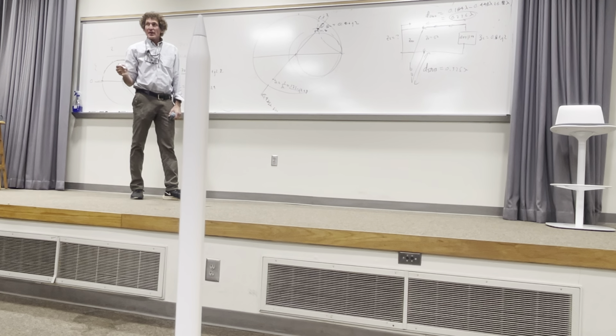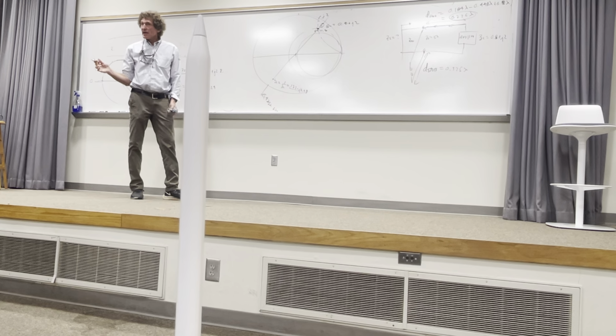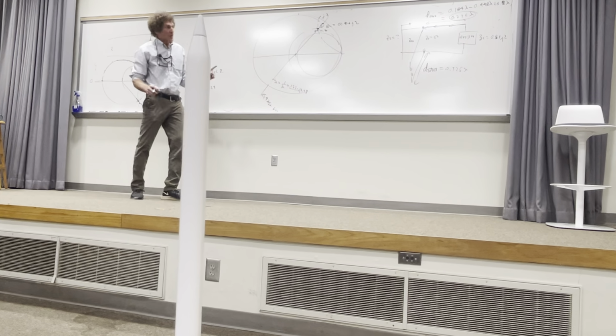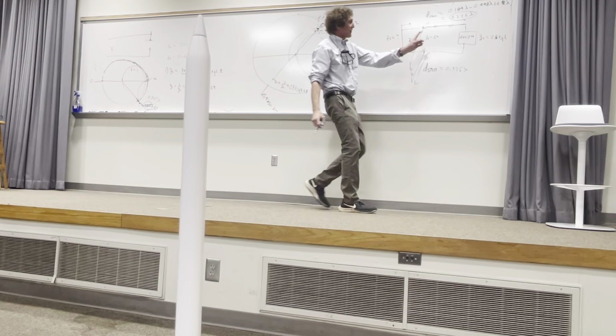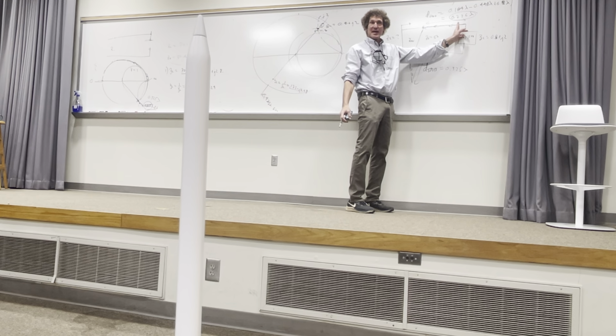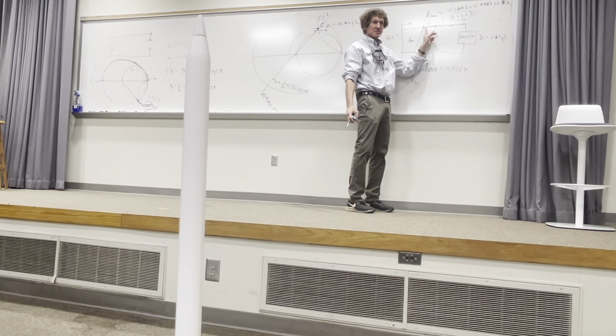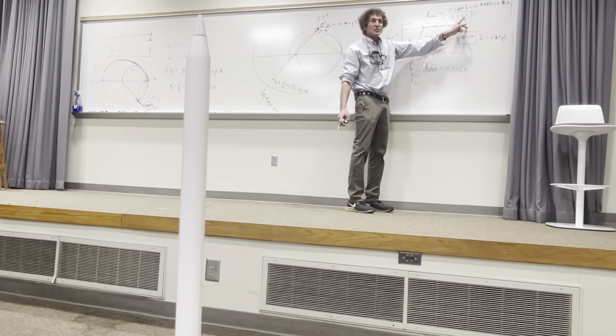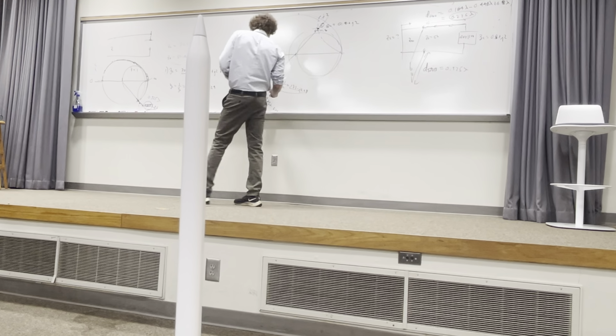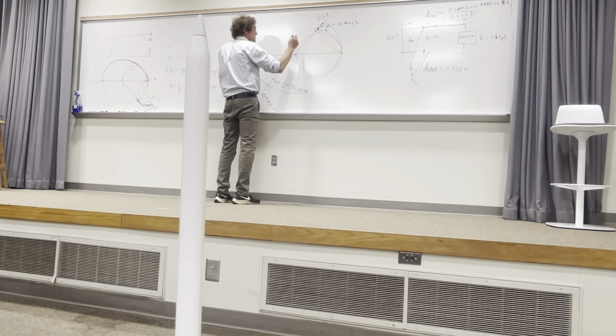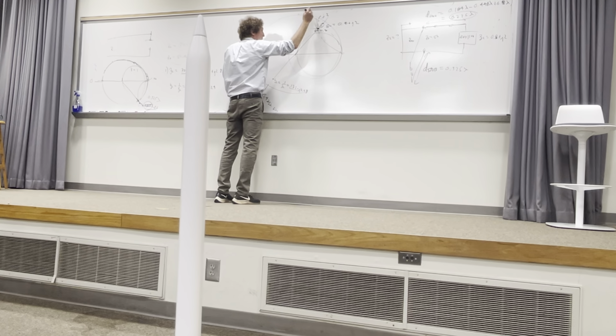Now, y'all with me? We had an old ZL, now I've got a new one. Everybody with me on this? Now, how far are we going to move from there? Do you all see he didn't change the length from the distance where the stub's attached? So now we've got to move 0.236 lambda. That's just shy of a quarter. So now we'll basically come to a new mile marker. I'm not sure exactly where it is, but it's about like here.